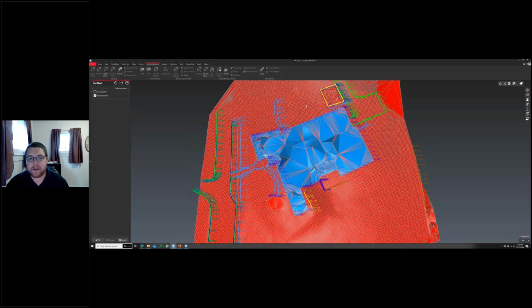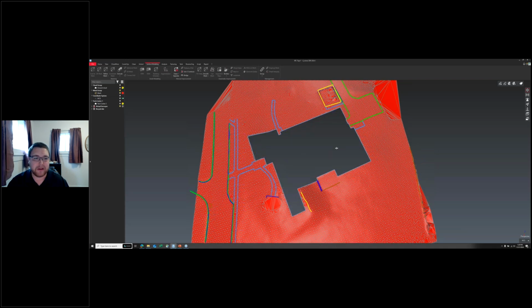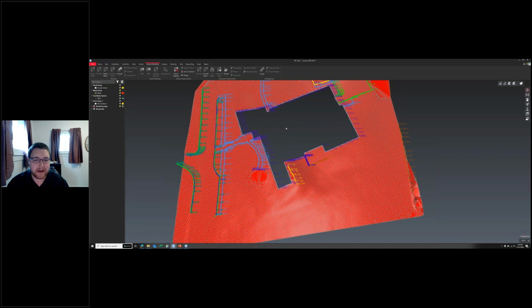So it turned into a red mesh and a blue mesh. They're totally different. That is pretty much like a bounding box. Every line inside of that mesh, it's going to remove for me. So I'm going to hit OK. I'm just going to select that middle one now, press delete, and it's gone. I cleaned out inside that building just like that. Nice, quick, and easy.